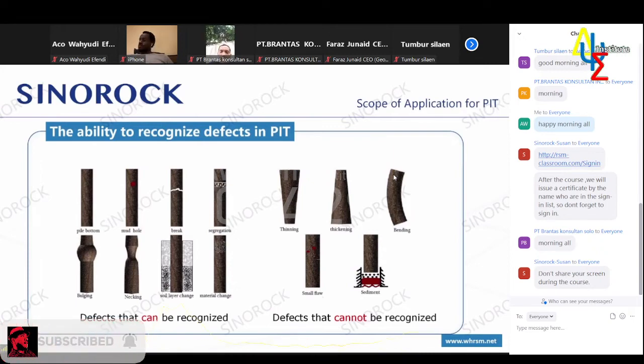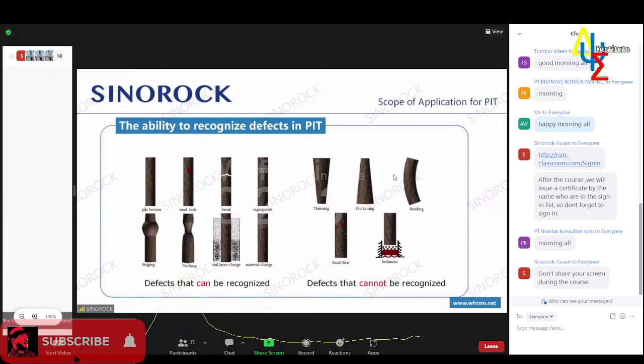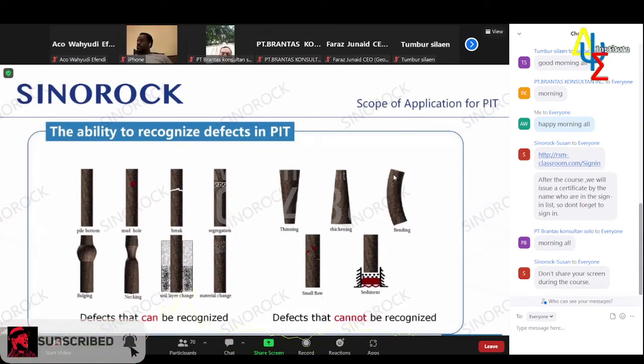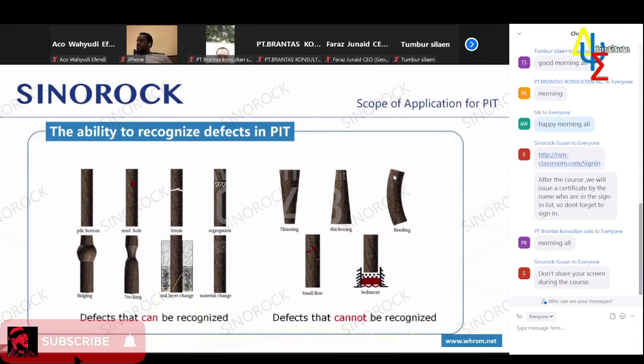The first one that is difficult to identify is the gradual process of area wave impedance. The low-strain PIT method can test some abrupt phenomena, rather than gradual phenomena. Gradual changes are difficult to reflect in low-strain PIT test. The second is a small defect. The key is whether the size of the excitation frequency can distinguish this defect. The sediment at the bottom of the pile is also a defect that cannot be identified with low strain.